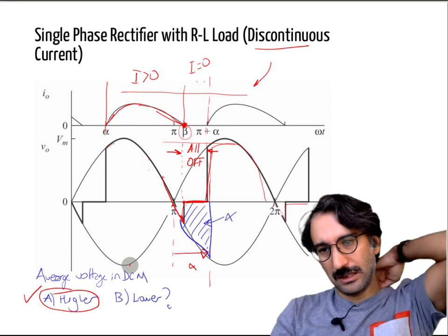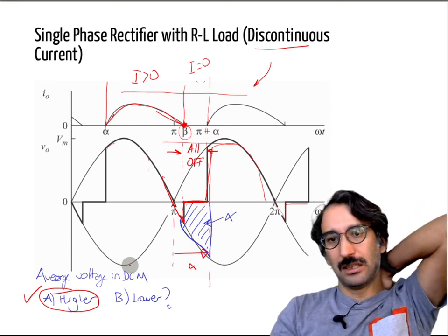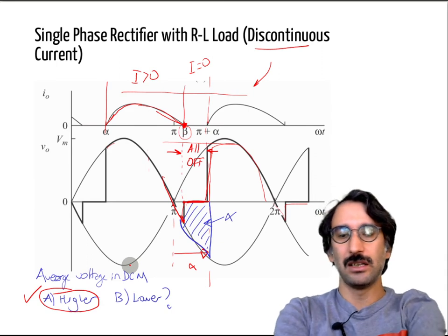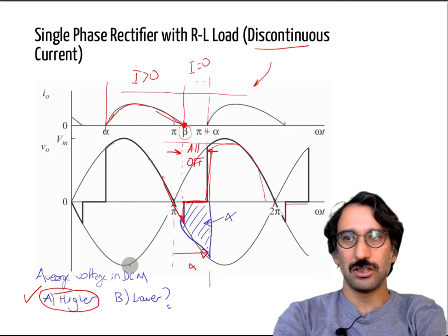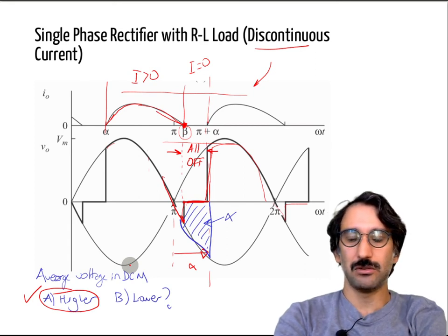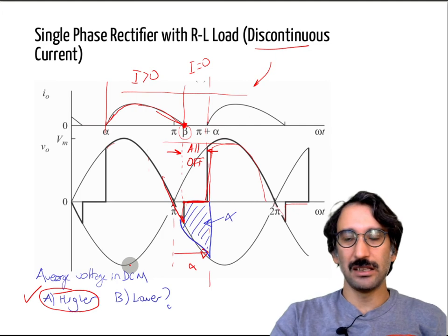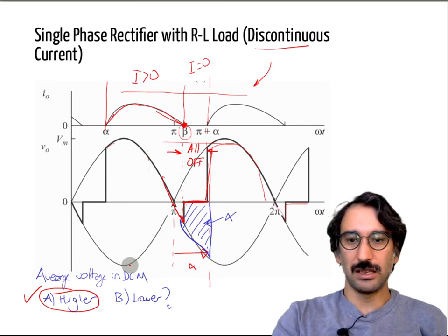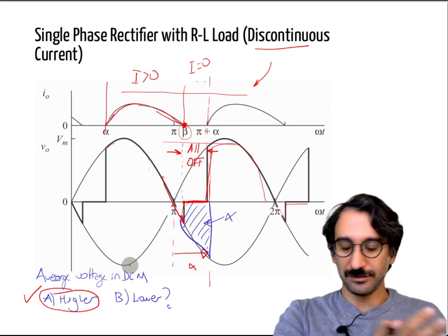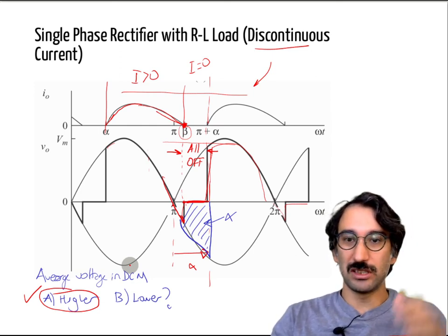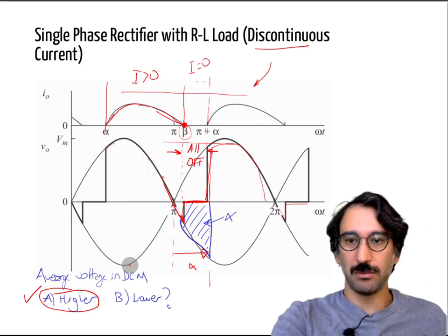Okay, so that is quite important for control, especially if you are working at lighter loads. Your voltage becomes non-linear. Okay, you don't have the same equation as with the continuous conduction mode. As a result, your controller should be measuring either the output voltage or current. Just applying 30 degrees of firing angle will not give you a specific voltage. It depends on whether your converter is operating in continuous conduction mode or discontinuous conduction mode.